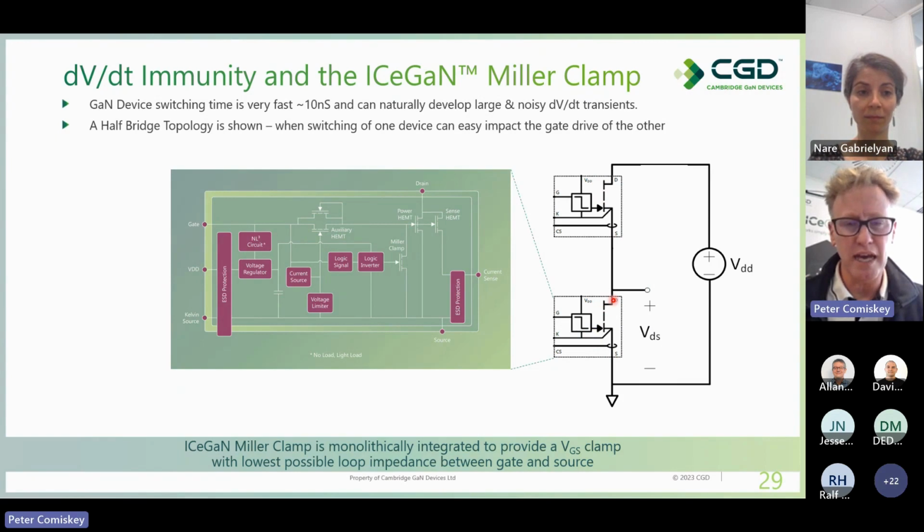And what can happen here is when your high side device turns on, the drain being initially discharged or low, you then present a very high voltage dV/dt transient to this point.